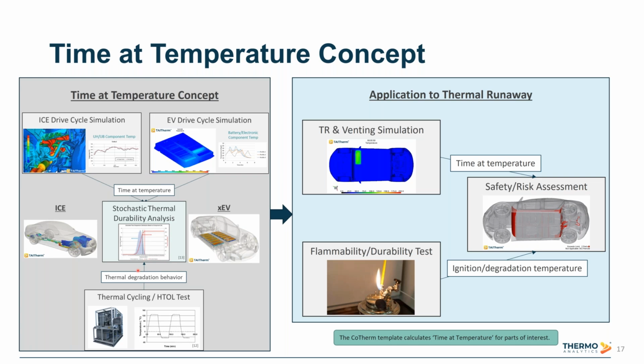Okay, and we can apply the same time and temperature concept here to assess the short-term durability of components during thermal runaway. And that's based on some information of ignition temperature or degradation temperature. And we can use the simulated time at temperature to then assess also the safety risk posed to vehicle occupants and first responders.